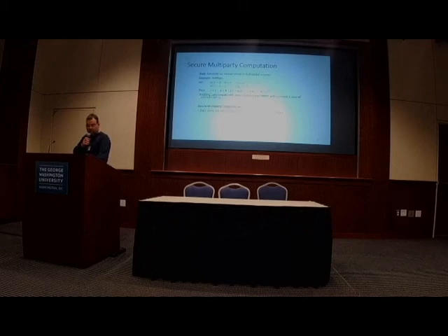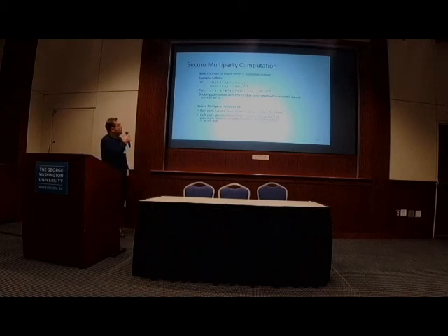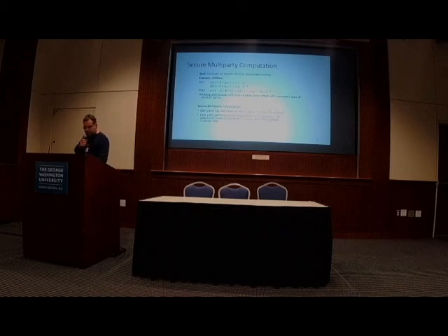This is the simplest instantiation, if you will, of classical Shamir secret sharing. If you don't want to do the first order, where you just XOR the data together, but instead you want T of them to be able to recover the secret, you use standard secret sharing, but this time you implement it in the computation path. You need to make sure that your computations still work, the addition and the multiplication, the XOR and the AND and all of that, so you need to recode the computation path.